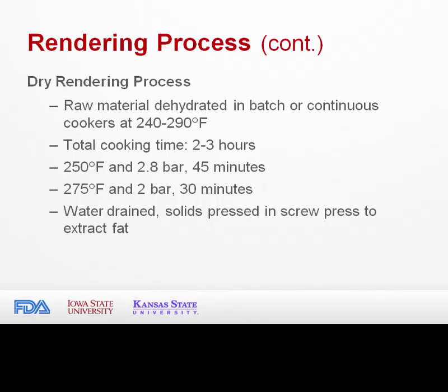After the dry rendering process, any remaining water is drained. The solids are pressed in either a single or double screw press to extract some of the fat from the protein components. Regardless of the method used, it is important to understand that the temperature and time of the cooking process, as well as subsequent steps to prevent recontamination, are vital to producing pathogen-free rendered products.